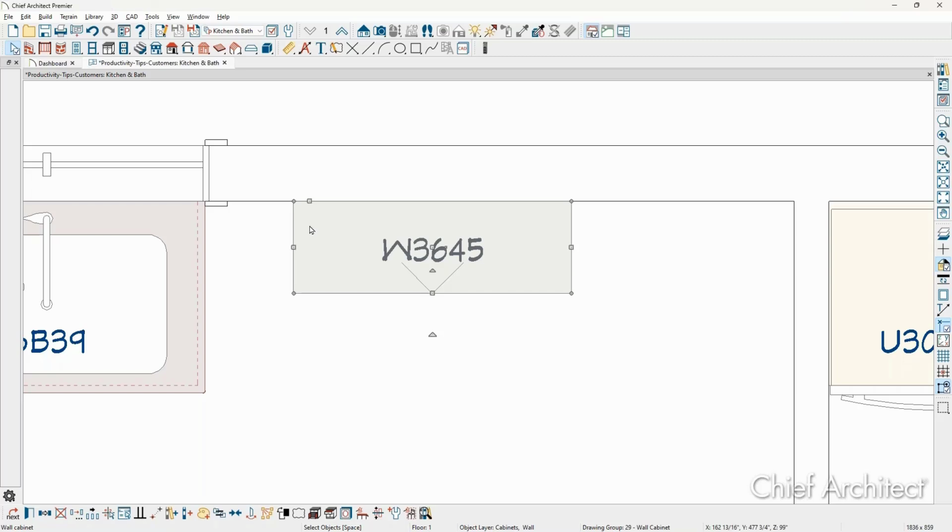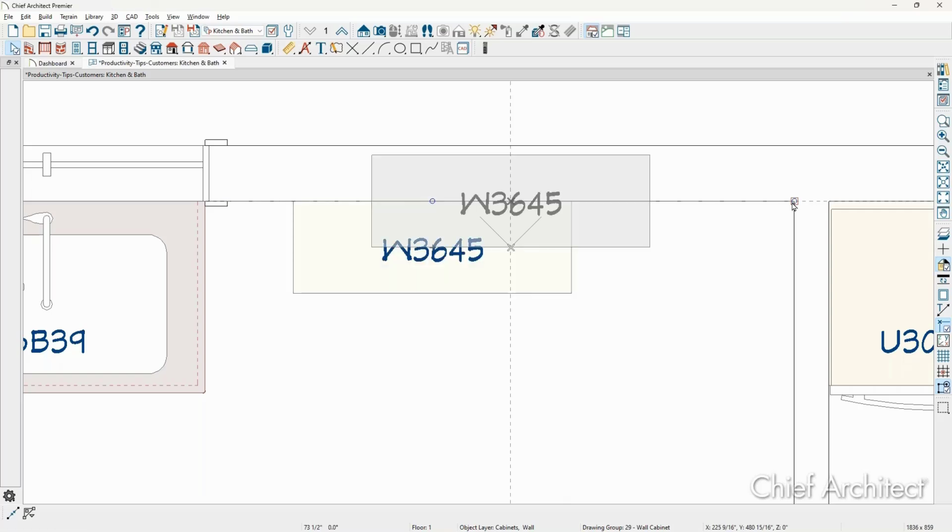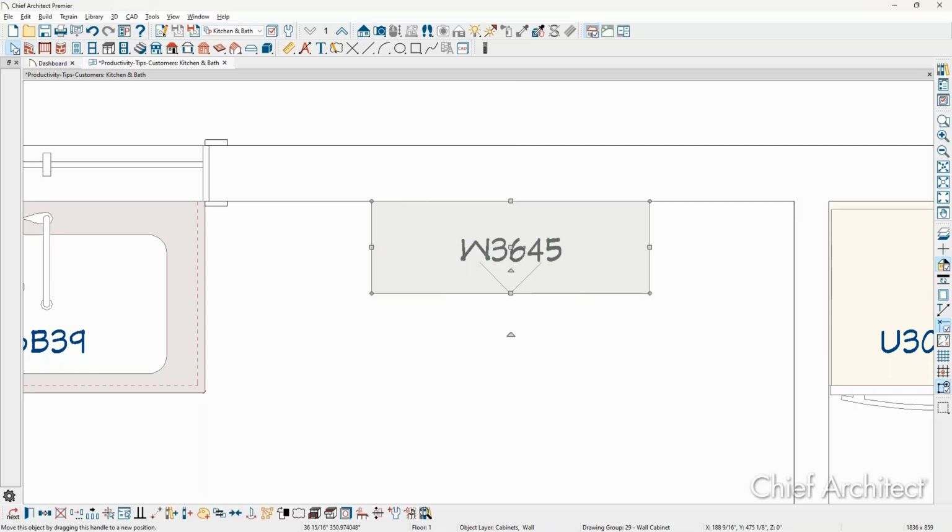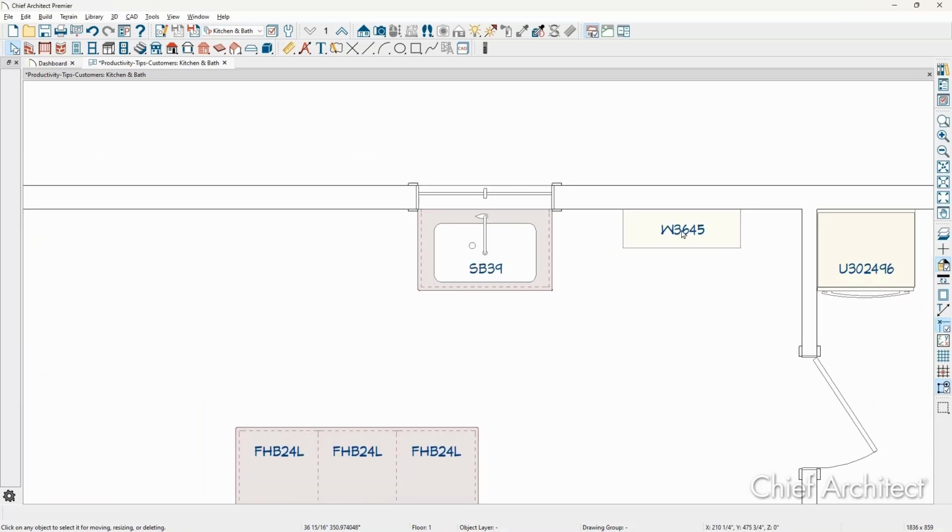Click on the object, use the center tool, and I'll do this slowly. Hover over the center tool, then in the far left-hand corner of my screen is a point-to-point center. And then I'm going to click on the casing, slide back over, click on the finish wall. It projects 2 points, and I'm going to go ahead and click right here. I now know that the wall space between the casing and the cabinet and the wall space over on this side is exactly the same.